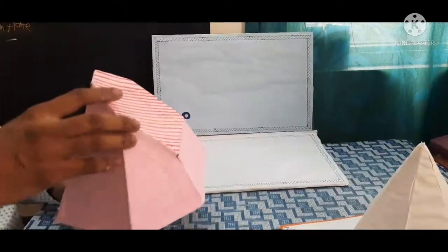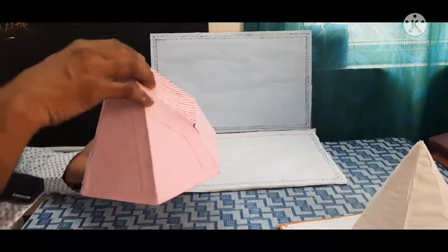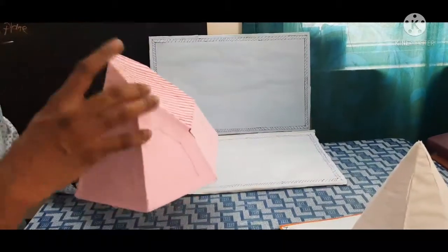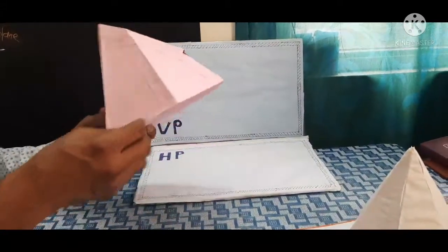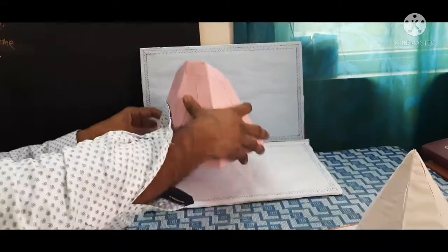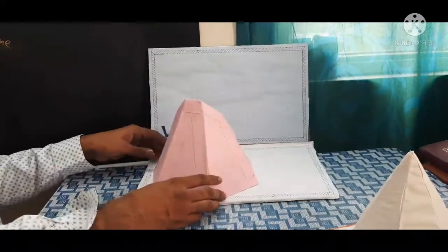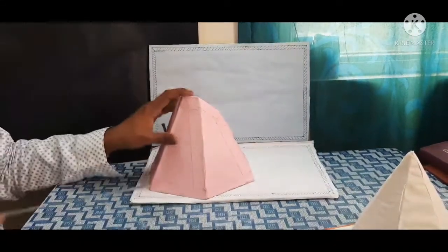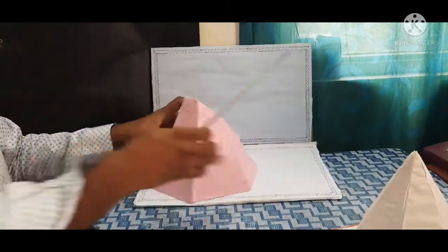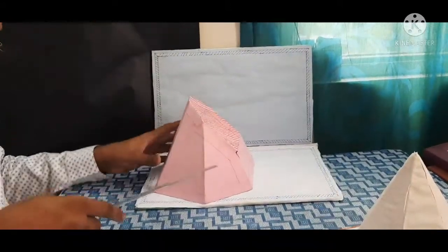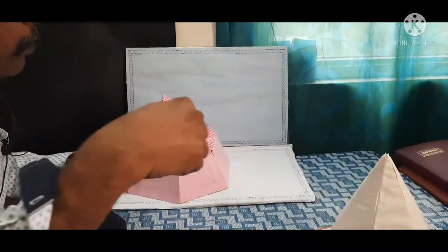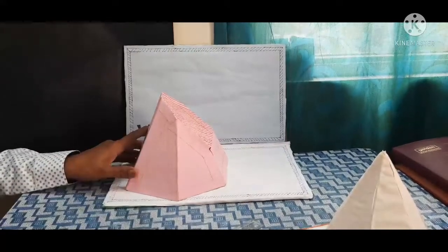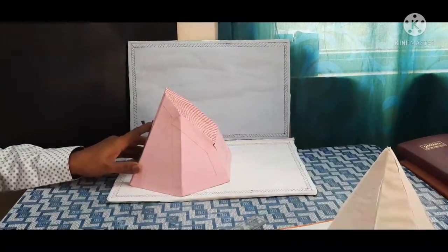Now our aim is to draw the front view, top view and true shape for this particular solid. That is our question. Now I am going to keep the two sides perpendicular to VP on the horizontal plane, the first position. First I draw the corresponding top view, then the front view. After removing some portion, while viewing the top view, this portion is the apparent section. It will be seen in the projected top view, right?